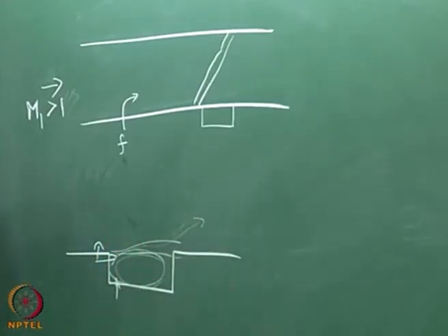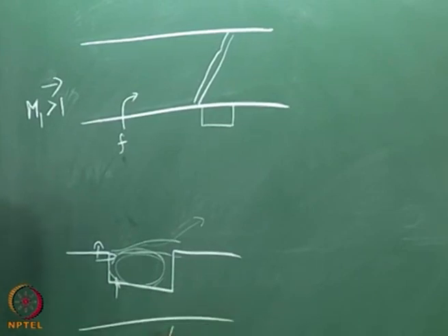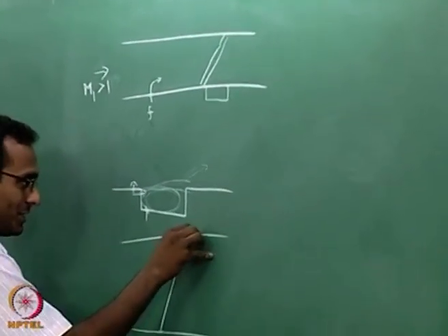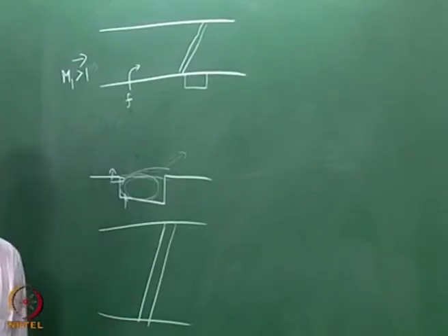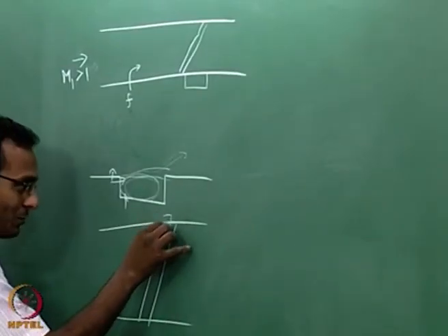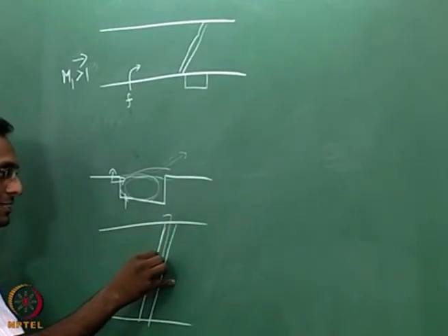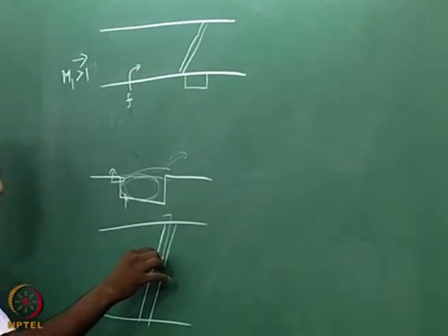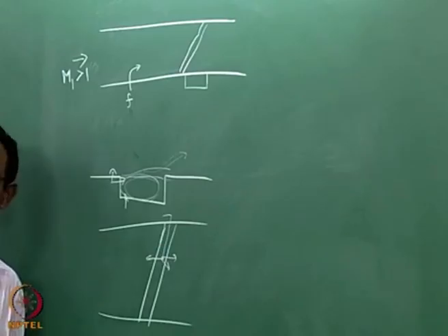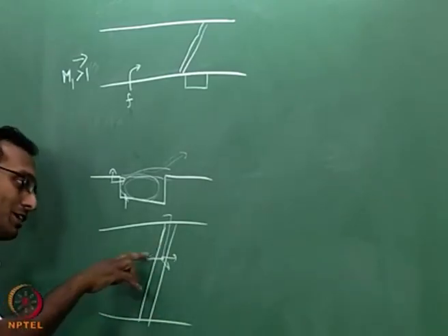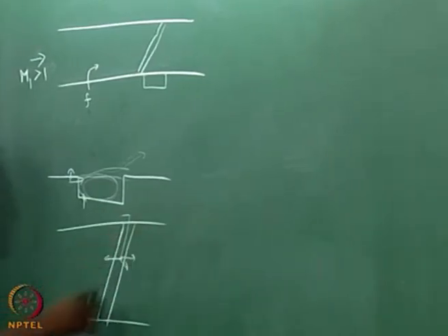Or I can have a configuration where there is a strut, which is just a metal rod sitting inside the duct, and I send fuel through this, and some holes in here will inject fuel this way, or to the side, or outward, somewhere along the direction, and now we think about how to mix this better along with the flow.